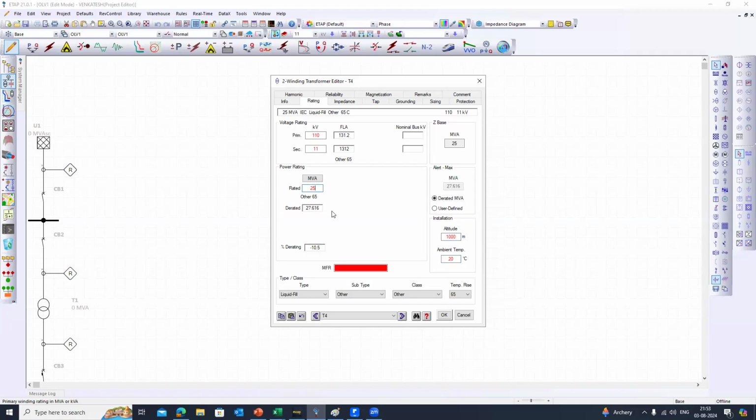So my second question: I'm controlling the temperature of the substation, that's not an issue for me. But is there any humidity issue? Outside temperature is 50-degree and inside temperature is 30-degree. Air conditioning itself means you are maintaining the ambient temperature. So as far as you maintain the ambient temperature of 30-degree, yes, you can use the transformer up to its full MVA, that is 25 MVA.